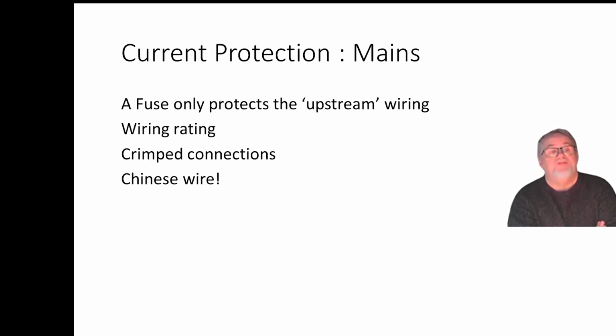But aluminium suffers from this weird thing called creep, whereby if you have a connection and it gets warm, or a piece of wire gets warm, then tiny fissures in the aluminium will migrate through the material, and they will migrate towards each other and coalesce, which means that the warm spot will get warmer, and as it gets switched on and off again and the heat keeps going on and off, these little micro fissures will coalesce into bigger fissures which will get hotter, and eventually this thing will get sufficiently hot that something will burst into flames.